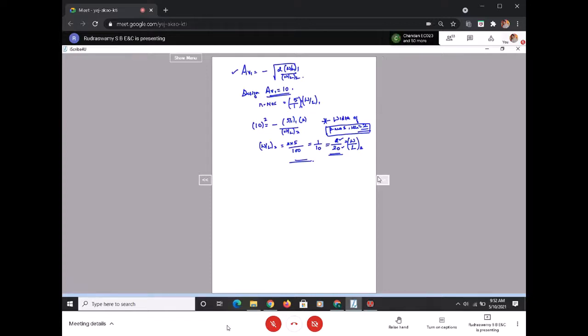So the very first analysis that we are going to do is the DC analysis. This is very important. DC analysis is with respect to the output versus input. So I vary the input in terms of DC from 0 to maximum, and I'll be checking how exactly it behaves.